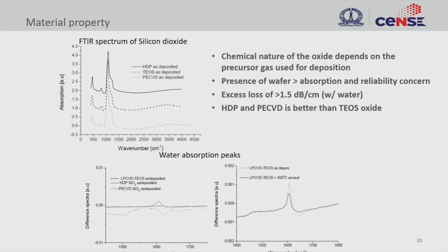So as deposited material, you see here a really flat line, and what you are trying to look at is the absorption here, right? This corresponds to water absorption, and when you see the as deposited film, you see a slight peak coming here. This is coming from water that is present in TEOS material. Unlike the other materials, you don't have any water absorption at all.